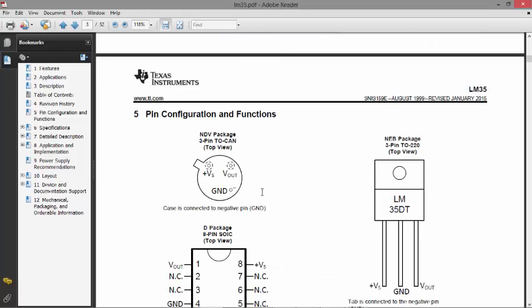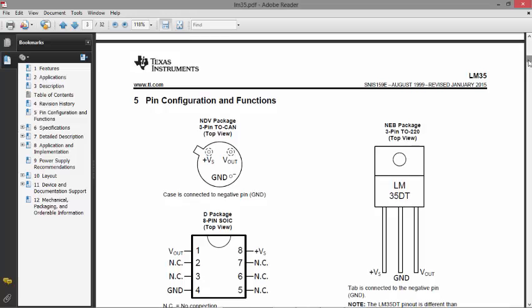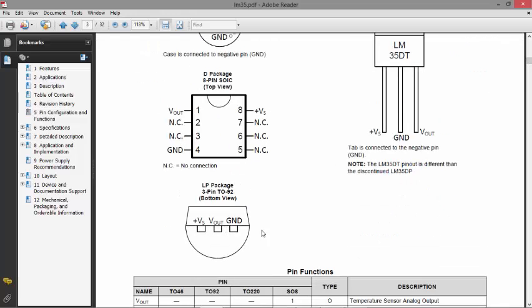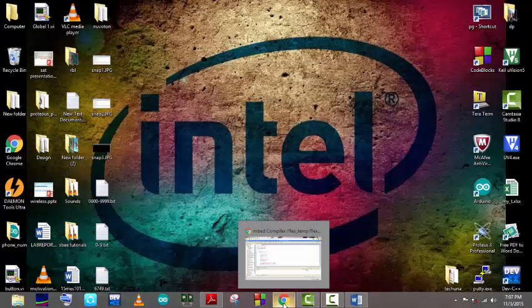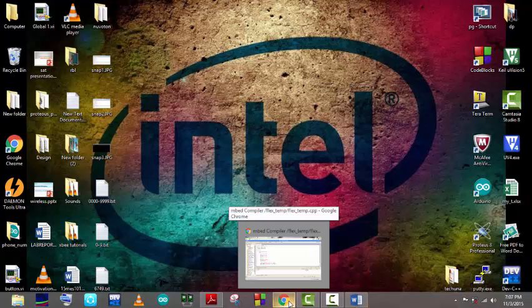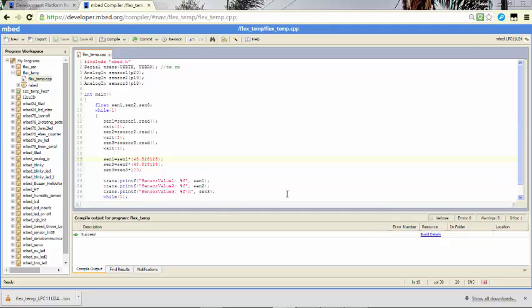And you can see my IC, the D is on this side, probably like that. So the first pin I have to connect to ground, the second one is my output pin, which will connect to the analog input pin of the board, and the last one is VCC. As per this I gave the connections, and finally I got the output. That is simple interfacing with the three different sensors with my board.